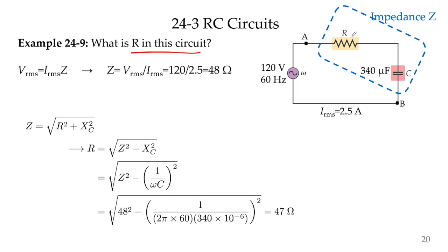Okay, so now what I can do is use this formula, which again looks like Ohm's law. In fact, the units of Z, the impedance, are ohms, just like resistance. And I'm going to use this. The impedance is the whole thing, right? Not just resistance, but the combination of these two.